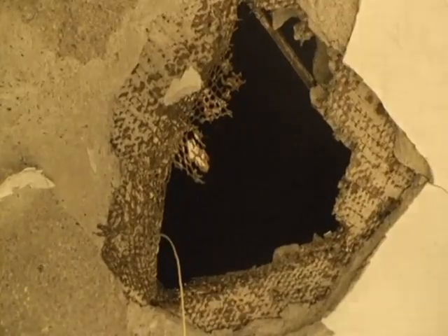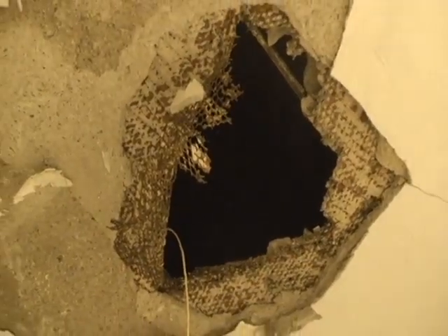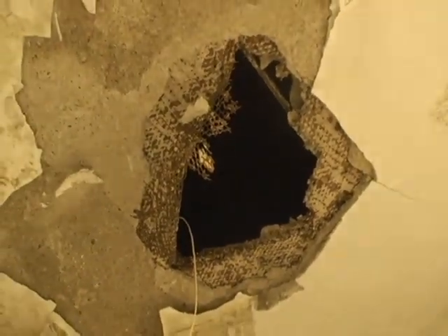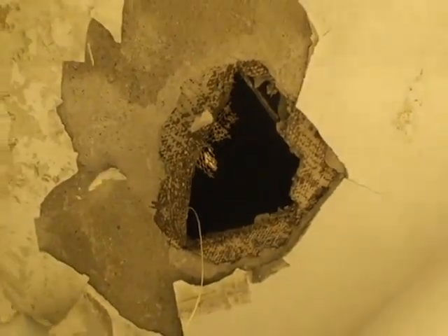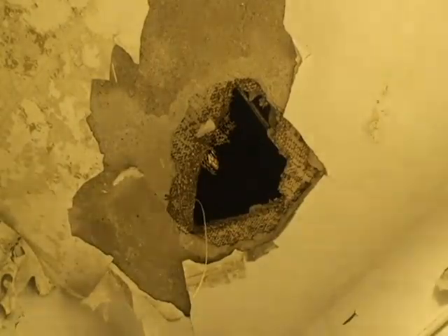If you look at ceiling plasters on profile, you'll find either a 2 or a 3 coat plaster. In older buildings, in metropolitan St. Louis or older municipalities like that, typically if you look at a piece of sample and you see fibrous material sticking out of it, it's not uncommon for that to be horsehair. You may find just a single layer of plaster on top of the metal lathe, or you could find multiple layers. If you find what they call a 2 or 3 coat plaster, generally if you find the asbestos, it will be in the last layer applied, the scratch coat.